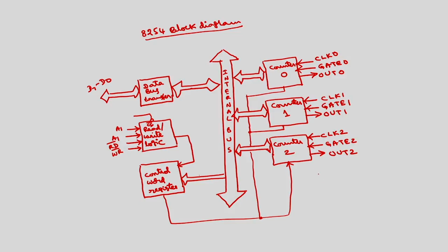Now, here you can program this. There are three 16-bit counters. We can count using BCD count or binary counting. And you can program this as timers also. The timers can operate in 5 modes. I will explain each mode in detail.